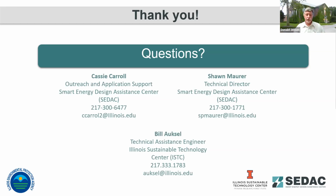We're also cautioned about harmonics with VFDs. Yeah, you definitely want to be using shielded power cable on your motors, your pumps. It's not always a problem, but when it becomes a problem, it's hard to identify and hard to pinpoint why your level sensor is now being funky or something like that, other equipment in the station.